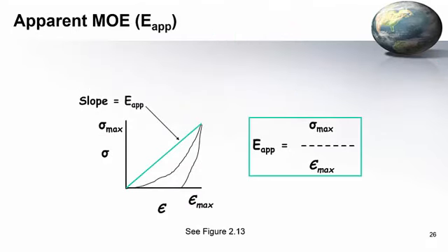So a lot of the time, this is the loading curve, okay? As the stress increases, the strain increases. It is not a linear curve. And when you reduce the stress, it comes back, and it may not come back to zero.